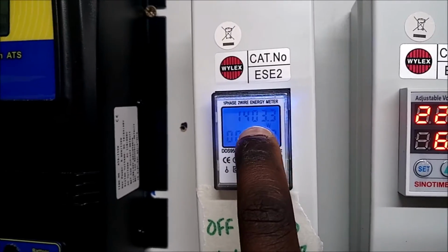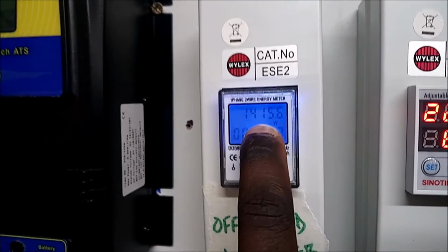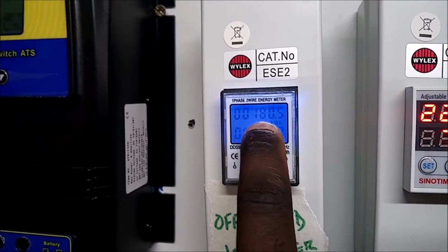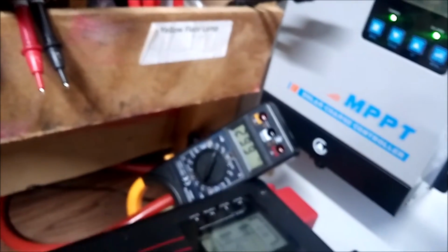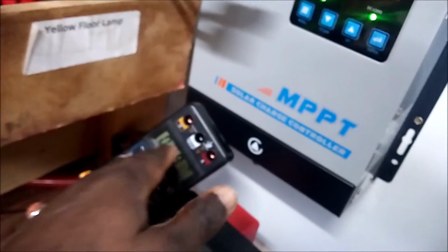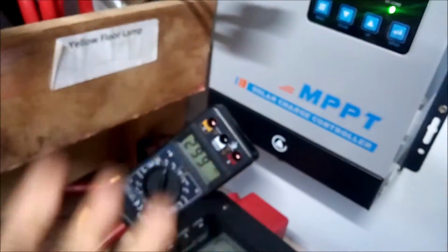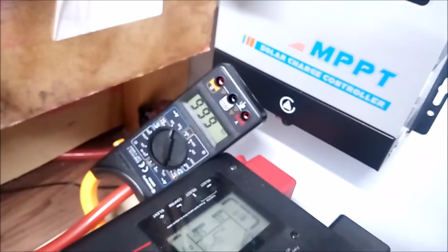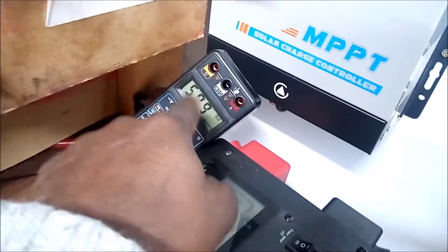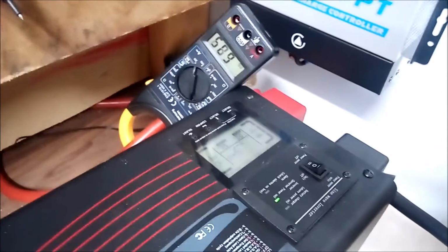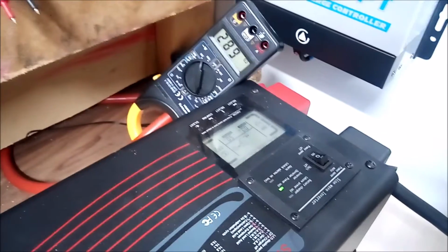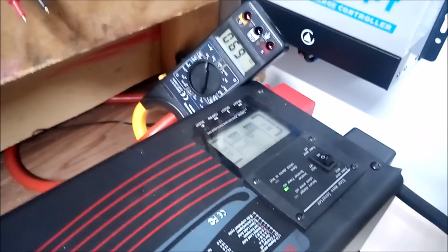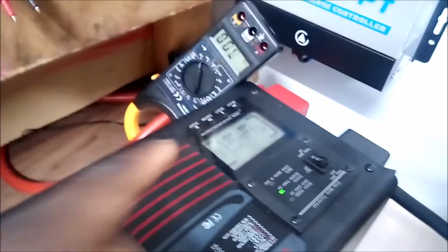So what you will normally do is divide this 1400 watts by your battery voltage, which is the 24-volt system that I'm using, and that will give you approximately the amount of amps you'll be getting from your battery. Now, the reason why this is high is because the inverter itself is consuming its own current. I think on standby it uses around 2.6 amps. So that needs to be added